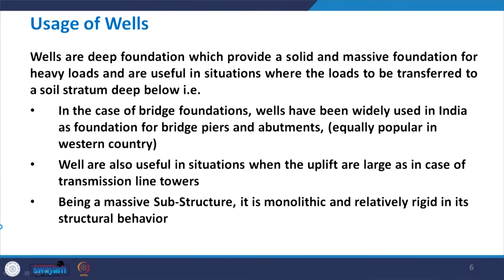However, the diameter of the wells is quite large compared to piles. As a result, they are able to provide a solid and massive foundation for heavy loads, including the loads of bridges. In the case of bridge foundations, wells have been widely used in our country as a foundation for bridge piers and abutments, and they are equally popular in western countries also.